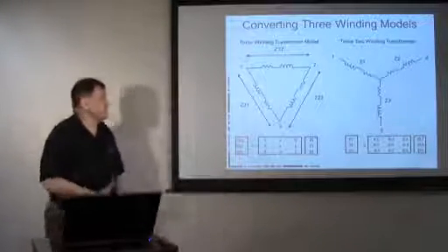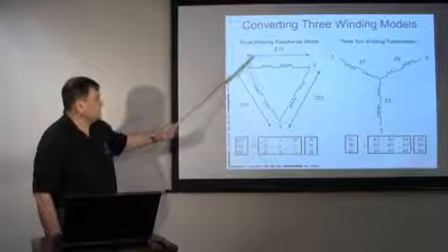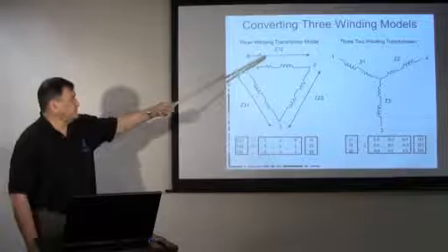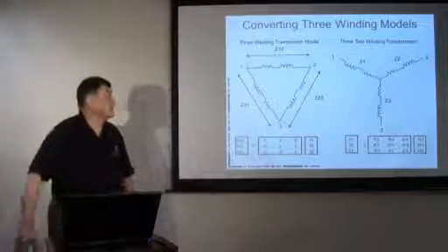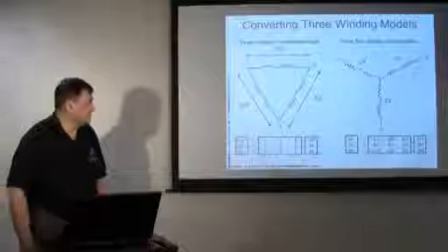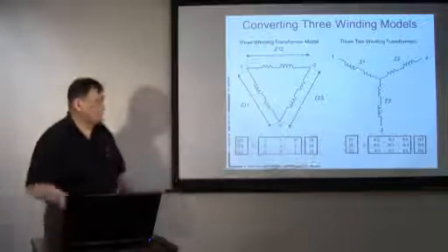And that's the same definition over here: what's the impedance, in other words, the voltage divided by the current flow if you have a connection across the primary and the secondary winding. So there's a little manipulation you go through: this matrix here is the inverse of this matrix. It's just a little step you have to go through to calculate these impedances if you're doing this modeling.